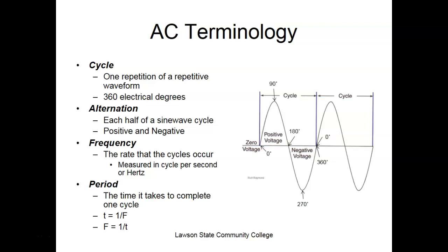So the power grid in the United States is 60 hertz. That means one complete cycle at 60 hertz only lasts 16.6666 milliseconds, and it's swapping polarity every 8.333 milliseconds. Milliseconds, guys. So for all practical purposes, this has no polarity. This is why it doesn't make any difference which direction you hook your meter up. Okay?